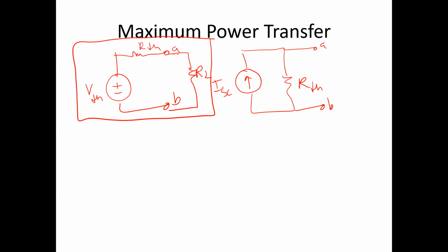And if you calculate the power being dissipated by the resistor, you can find that you will get the maximum power when the Thevenin resistance is equal to RL. Again, what Thevenin resistance? It's the Thevenin resistance of whatever is connected to RL. And that is what we found in the previous parts of the problem, which was 24 divided by 11 kΩ.